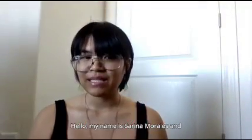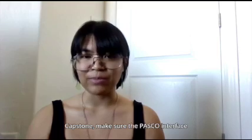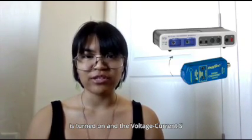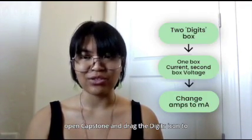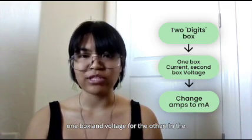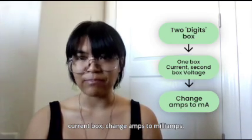Hello, my name is Sarina Morales, and these are the procedures. To set up Pasco Capstone, make sure the Pasco interface is turned on and the voltage current sensor is plugged into it. On the desktop, open Capstone and drag the digits icon to the center twice. Select current for one box and voltage for the other. In the current box, change amps to milliamps.